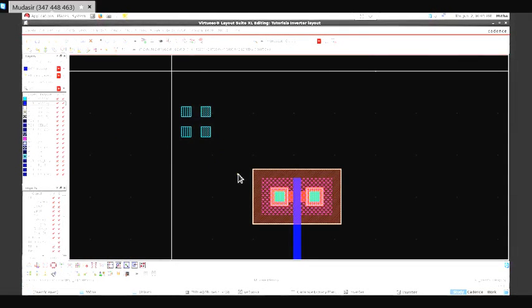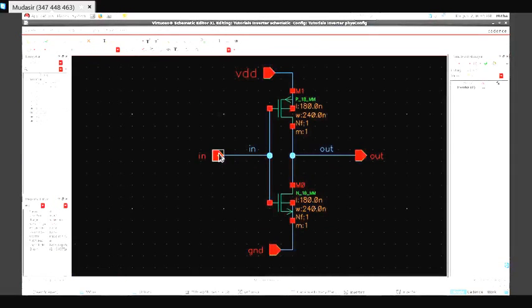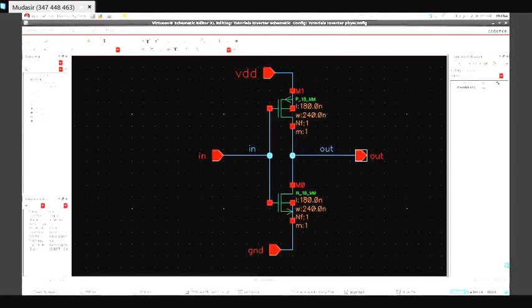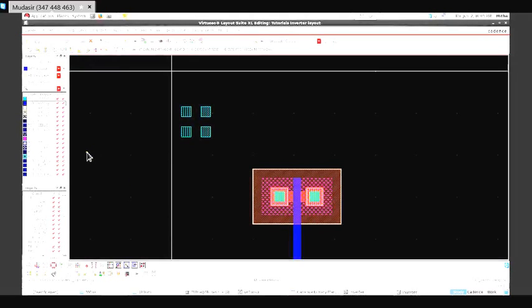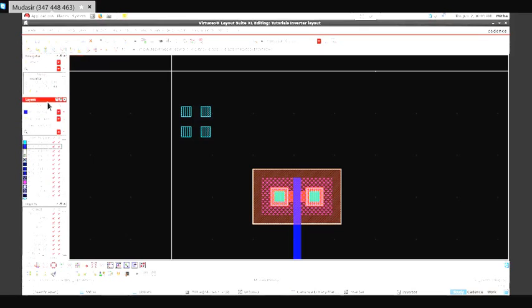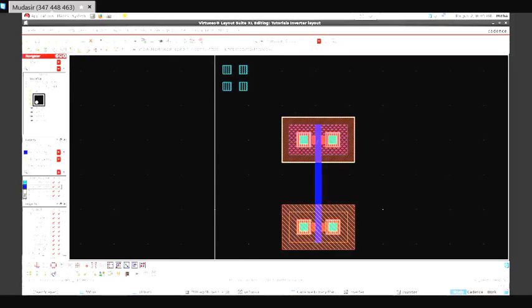So these are the different pins. Now one more confusion is which is which pin. Whether this is VDD, this is ground, I can't define from here. So one way is I will click on this and go to my schematic. It will show me, okay, this is in. Similarly, if I want to see what this pin is, I'll click on this one, go to my source file and see, okay, this is the output pin. This is one way. Another way is I'll click here, the navigator is there, this one, it will show me here. I'll pick ground, so this is ground. It also shows the connections that I have to make for in, for out, for ground.